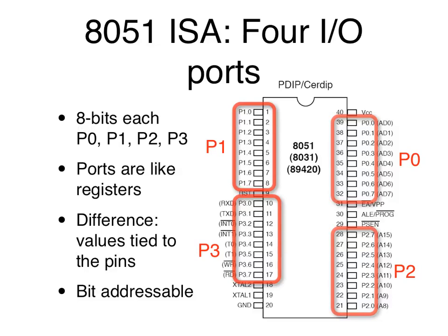I mean, you need a power and ground, so you minus 2, and that's only 6 pins left for all these other functions. And 2 of them are for the crystal. Okay, 4 other pins, and those are really just for supporting external memory. So everything else goes to GPIO. This shows you how important GPIO was, at least at that time.